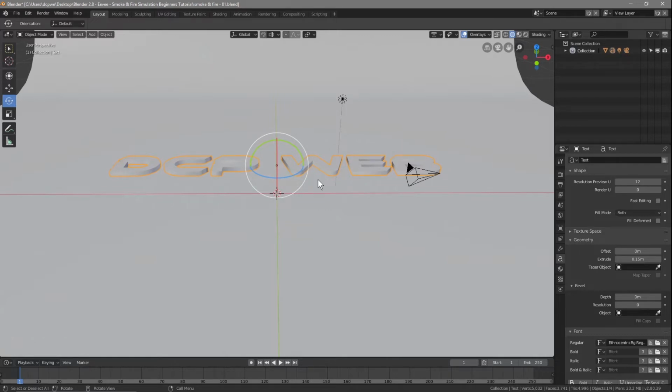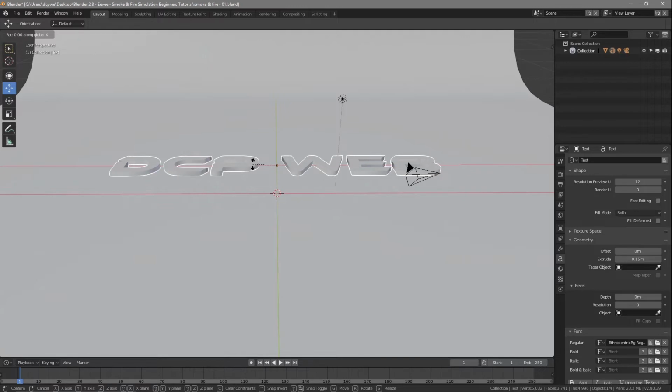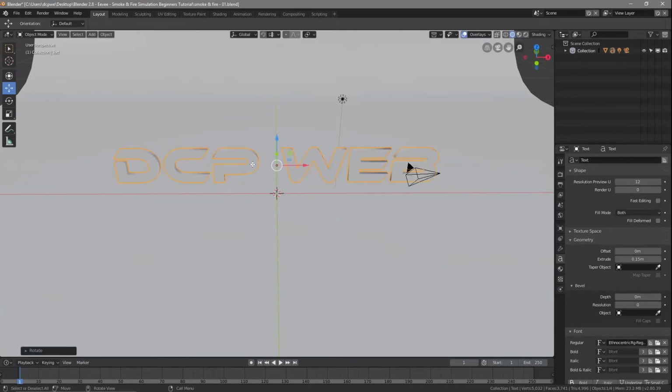And we want to rotate it on the, if we move back to the move tool, click here. The easy way to rotate things is to press the letter R, but understand which direction you want to rotate it in first. So we want to rotate on the X axis along the width, right? Along the horizontal. So we press R, then X. You can see the line goes red through this text, and then we're gonna rotate it 90 degrees. So if you remember them shortcuts, S to scale, R to rotate, and G to grab, get used to those shortcuts and that will help you a lot.